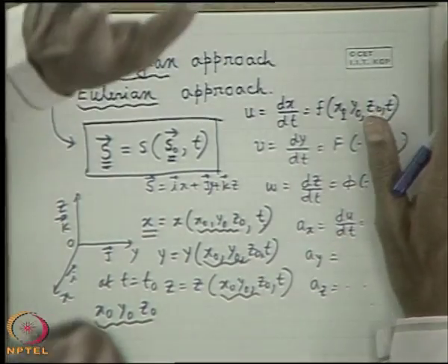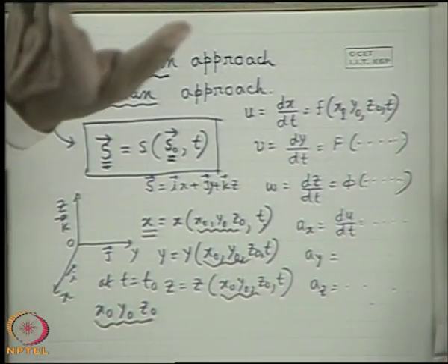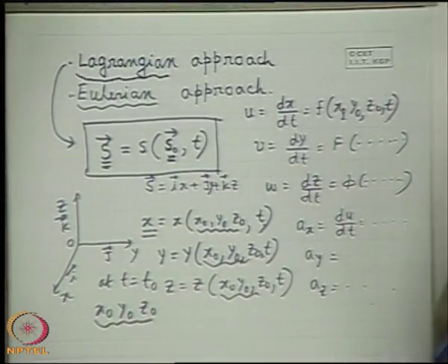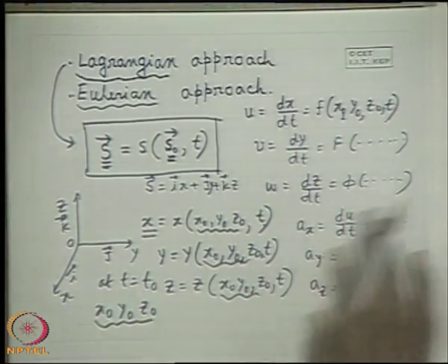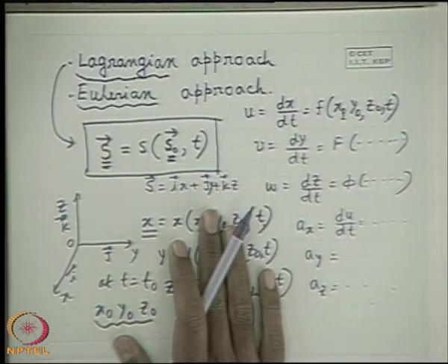This approach is very fundamental in nature because it traces all the fluid elements that compose the flow. And one very important point of this approach is that the conservation of mass is inherent in the Lagrangian approach, because when a fluid flows, the mass has to be conserved. The kinematics of the flow must obey the law of conservation of mass. So, conservation of mass is automatically checked because each and every individual particle is traced.